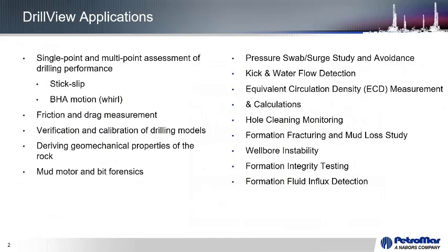Let's talk briefly about DrillView applications. Those range from drilling dysfunction mitigation, stick slip, whirl, characterization and mitigation of friction and drag, especially if we have multiple tools in measurement along string mode. Verification and calibration of drilling dynamics models is a common application of this kind of data. Derivation of geomechanical properties of the rock, both from the vibration and also in conjunction with the spectral gamma ray data.